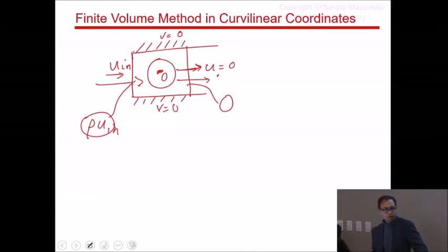Okay? So what will that do? You know from Newton's law, change in momentum is directly proportional to the external force, right? So what this will do is make the flow accelerate heavily in that iteration, because there's this change in momentum that has to be balanced by something else. So in this case, basically the pressure. So whether you look at mass conservation or momentum conservation, on one face I have a huge value, on the other face I have no value, and that causes immediate problems.